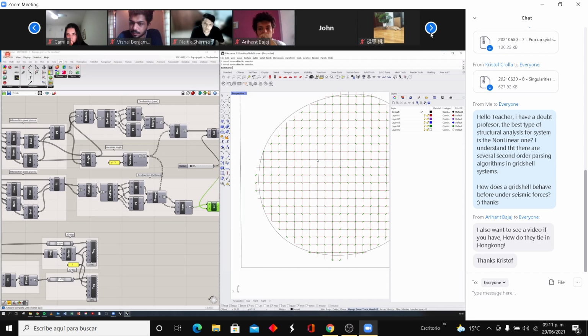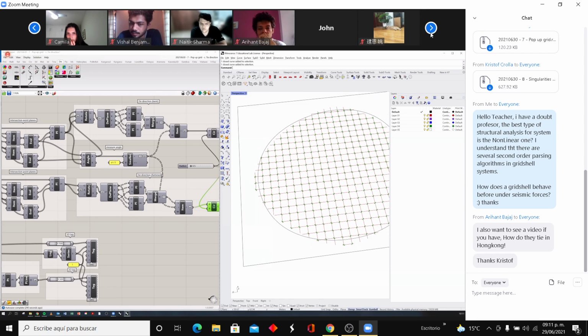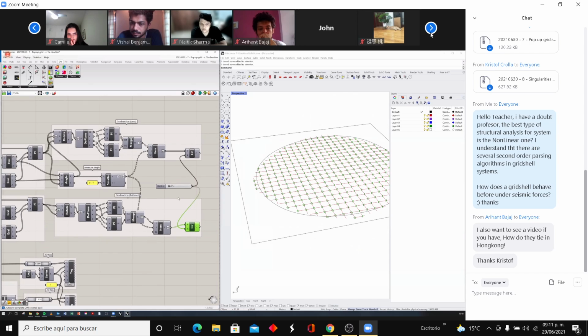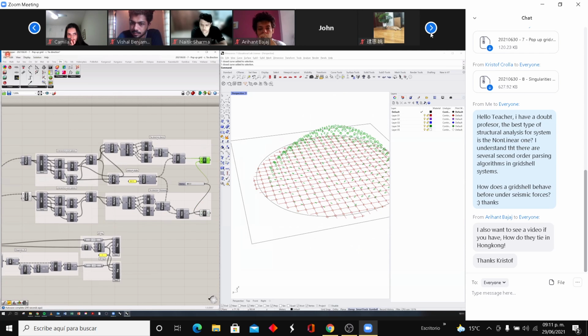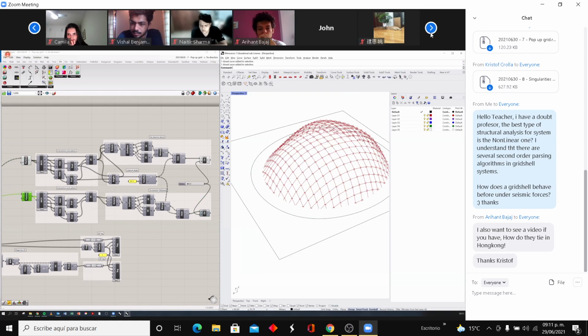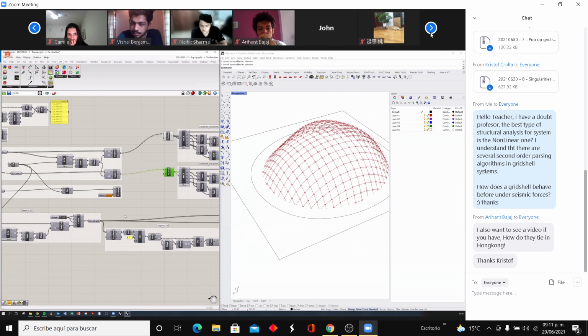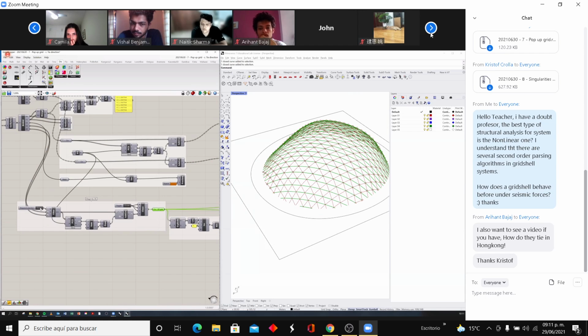If I were to choose that as a strategy, now everything will move quite loosely. And then once it's popped up, it will be like this. And then once we have that built and that works, we'll just add diagonals to stiffen the whole thing. This direction or this direction, you can choose what it is that you want to have. So that's the second knot. You don't add the diagonals until your whole system is deformed, because diagonals lock everything in place.